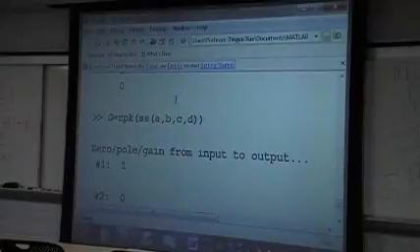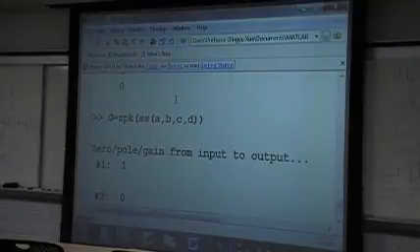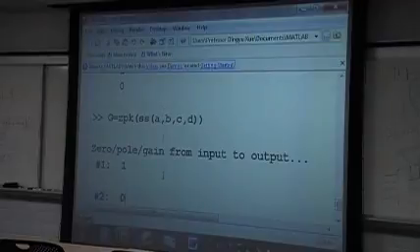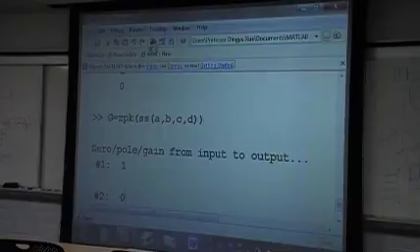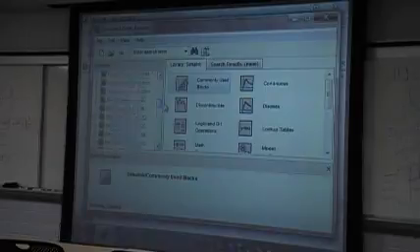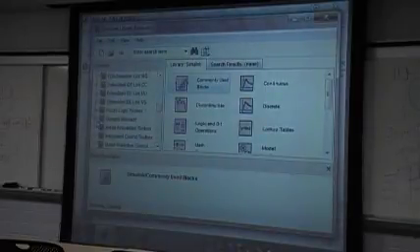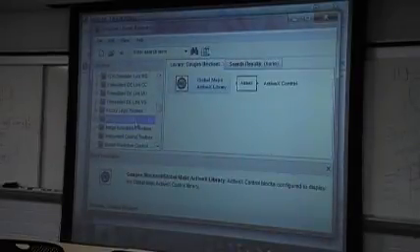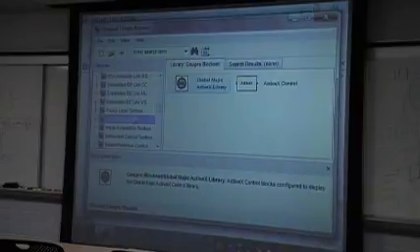I've shown a lot by using the scopes. Here, I want to explain more on the display of signals. So let's go to Simulink again. We will see that there is a group called the ActiveX block section.